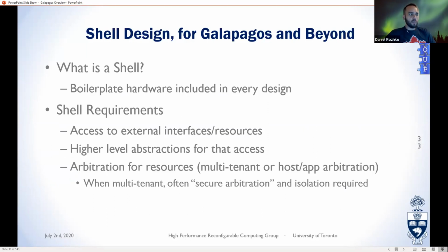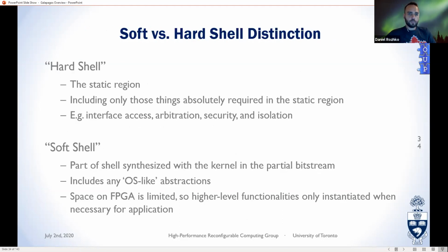And then there's also arbitration for those resources. Typically that's in a multi-tenant shell where you have multiple applications on a single FPGA, but it could also be host and application arbitration. Something to note is that in a multi-tenant environment, we also have security hardware and isolation hardware that we implement, and that's work that we've done in our group as well. So we do have that kind of hardware in our shell.